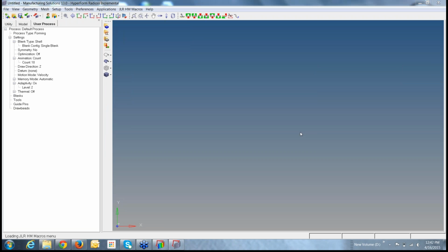Depending upon your geometry, you can use the outer skin as die and the inner skin as the punch. So if you are extracting, you can use the top skin as the die and the inside bottom skin as the punch surface.